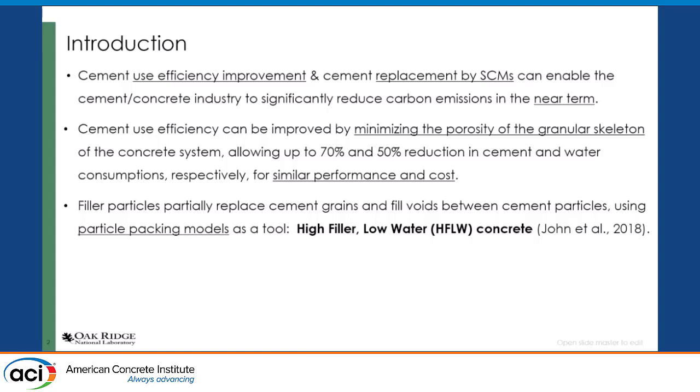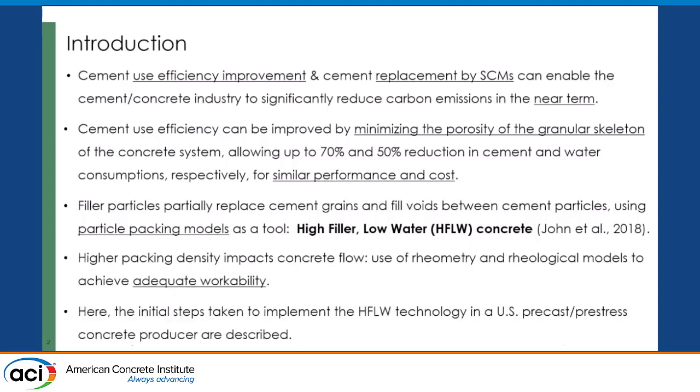So we use particle packing models and mobility models, and we develop what we call the high filler, low water, or HF LW concrete. And this technology has been described by Professor Vanderlei John and his group in 2018, a publication from CCR. The thing is, when we increase the packing density of the system, you expect that the rheology is going to be affected. So throughout the whole project, we need to keep an eye on rheology, make sure it's working well. So here I'm describing this effort to implement this technology in the US precast prestressed concrete industry.